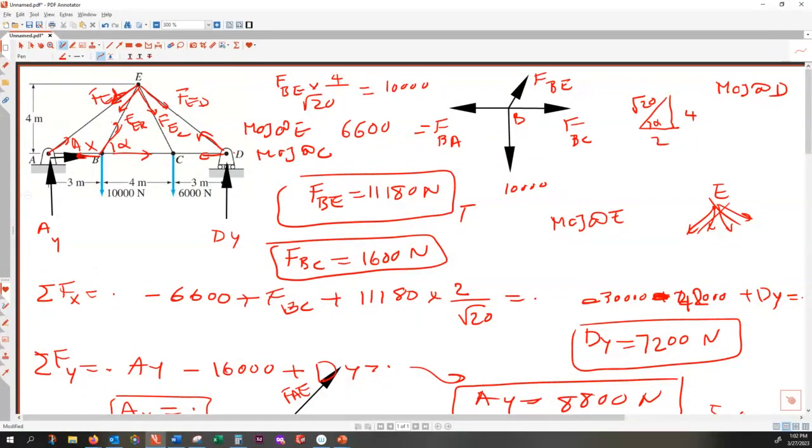If I get something different, that means I have to go back and find where I made a mistake. So when you do the method of joint, the last step would verify your solution. There is no unknown. Everything is known, but just checking whether they sum up properly, that is to check your answer.